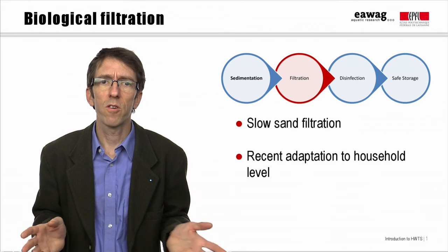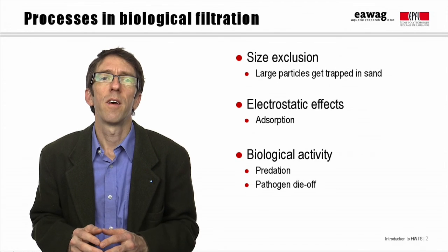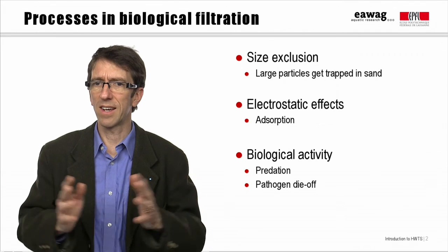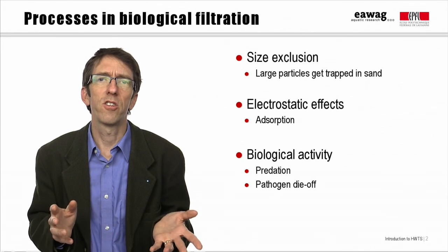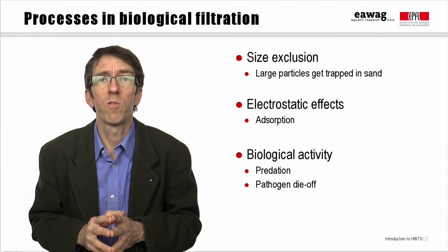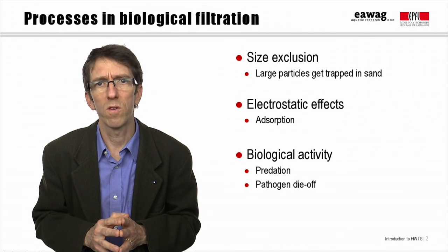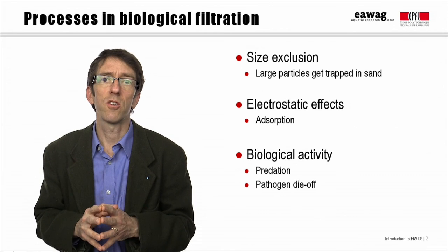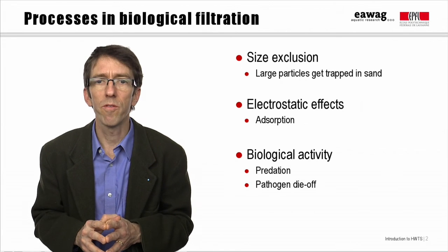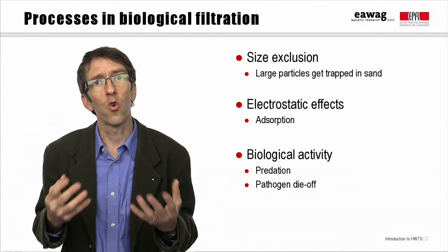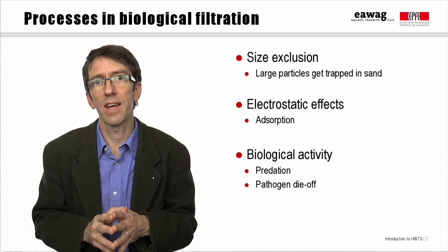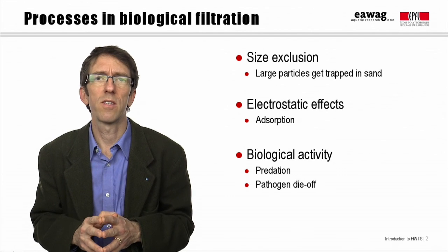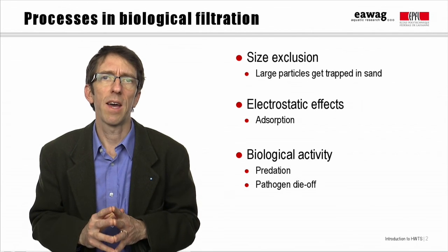We saw in the membrane filtration lecture that sand filtration alone can remove large particles through size exclusion, but that pathogens and even relatively large protozoa are still smaller than the pore spaces and can pass through. Some pathogens will attach to larger particles which are removed, and some pathogens will adsorb onto the surfaces of the sand due to electrostatic effects, but rapid sand filtration has only a small impact on pathogen loads.